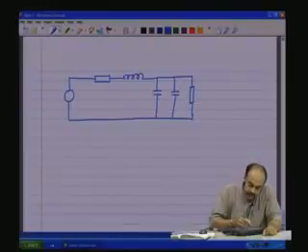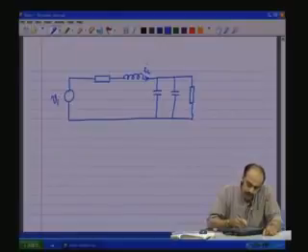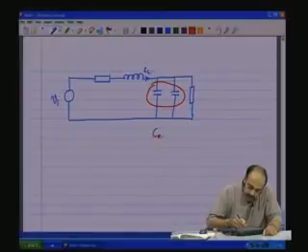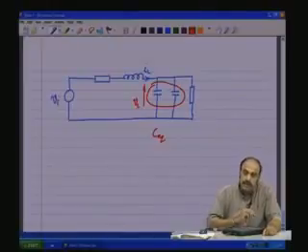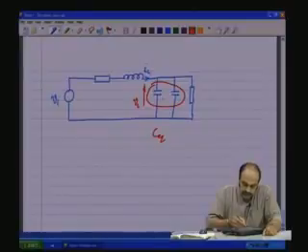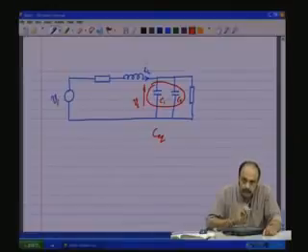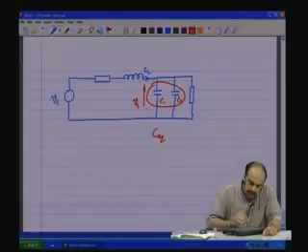So I have a state variable here IL, we have Vi. Now either we combine C1 and C2 and make it a C equivalent and have one common state variable Vc for that, or associate Vc with either C1 or associate Vc with C2, any one of them. So there will be only two state variables, a Vc and an IL.